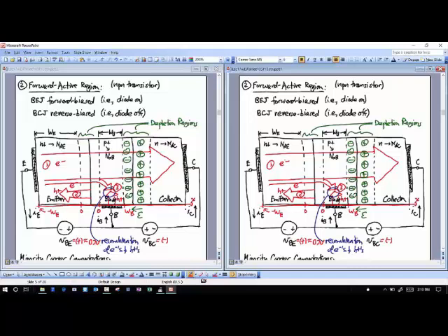They start from the emitter side and get injected into the base. That happens because you put that 0.7 volts or more across this base to emitter junction. You forward bias the junction. That injects electrons here to the point where the concentration of electrons is higher just at that point, right at the junction, than anywhere else in that base.